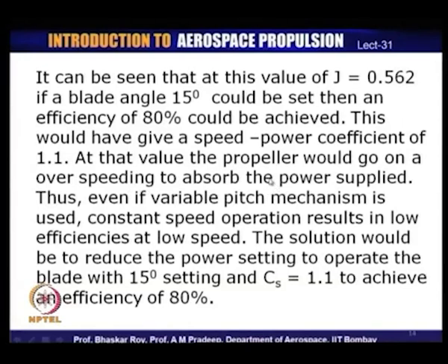We had already specified the amount of power available and the gearbox ratio, and if you use those values as your input power, you would arrive at a situation where the power the propeller needs is less than the power being supplied, and this would result in overspeeding of the propeller. This overspeeding is not a good idea. The propeller would get hugely stressed due to the overspeeding, and as a result the propeller might break.